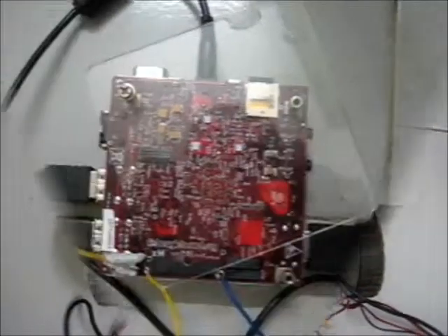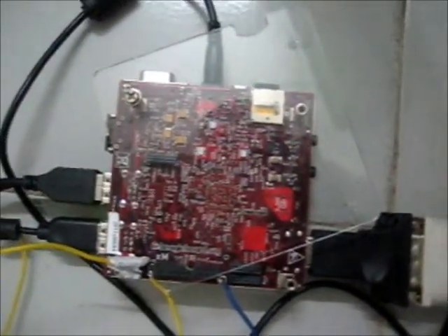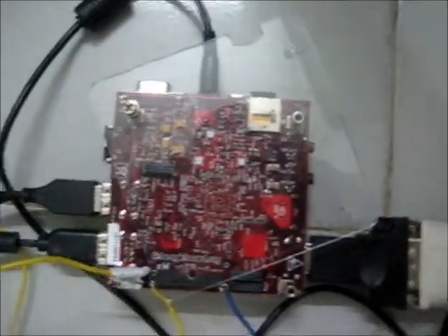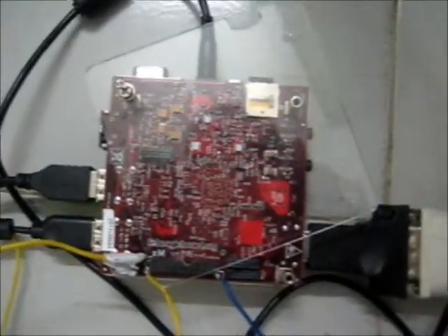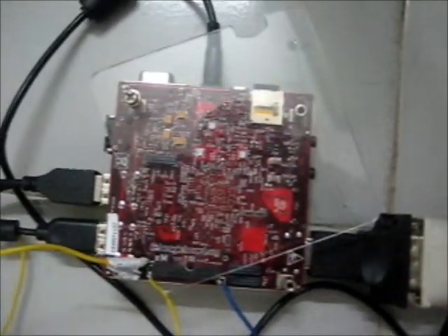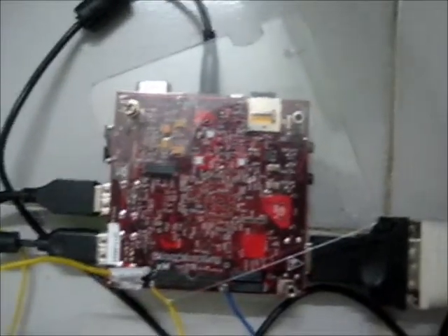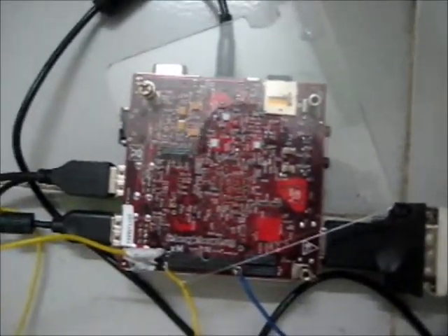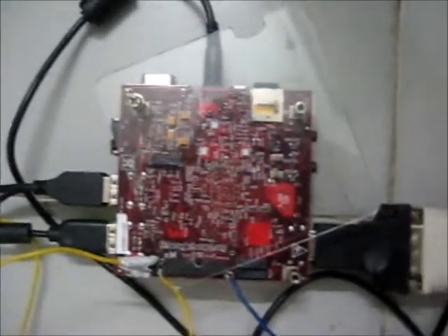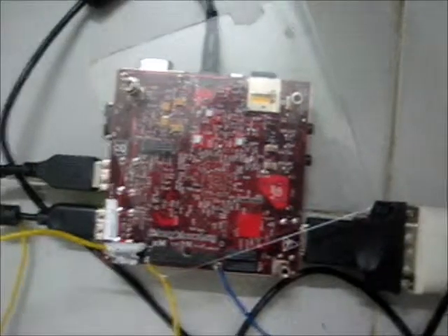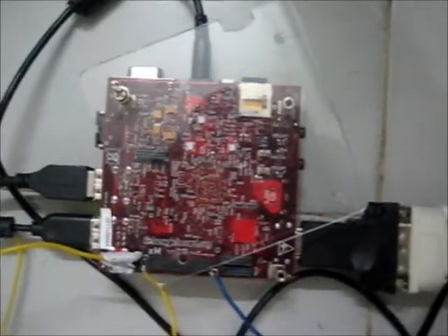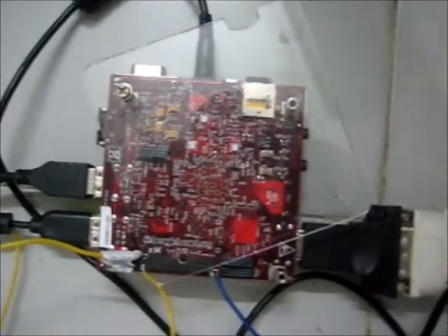The BeagleBoard is an ultra low cost, high performance, low power OMAP 3 based platform from Texas Instruments. It is the central processing unit of the entire system. This unit analyzes the images received from the webcam and detects obstacles in them. The board also receives signals from a sonar module. Based on the input from the webcam and the input from the sonar module, the board outputs several control signals which are sent to the motor driver module and the vibrators.